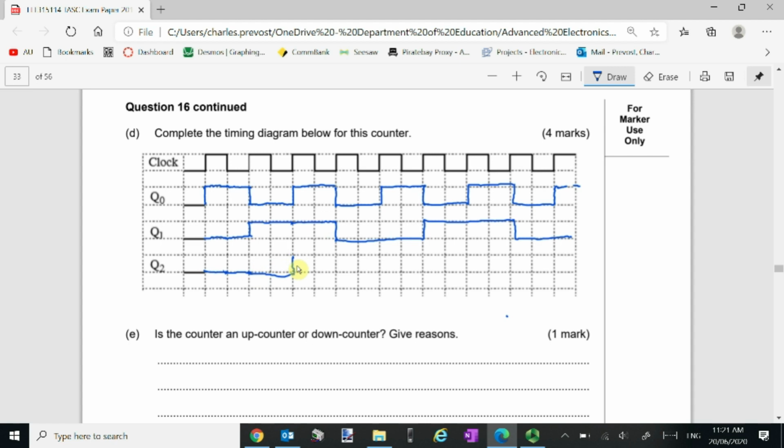Okay. Oh, oops, it's not there. There, that's the next one across. So both Q0 and Q1 are 1, so now it's going to tell it to change. Okay, now it won't change again until Q0 and Q1 are both 1, and we get the clock there. You can see now we've got this 8 pulse.